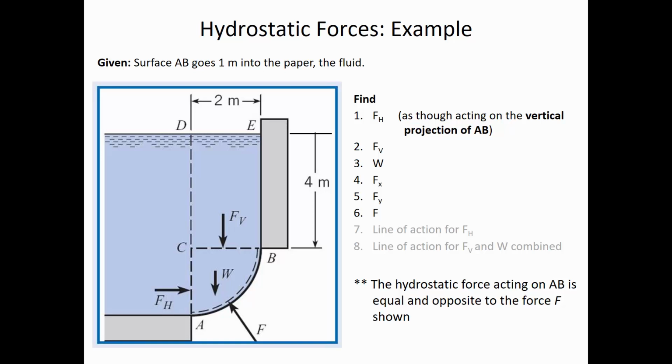We can start with the horizontal force. And the horizontal force, remember, is all based on the vertical projection of the curved surface. And so we just pretend like there's a gate in the water, and we want to find out where is the location of the force acting on that projected gate.